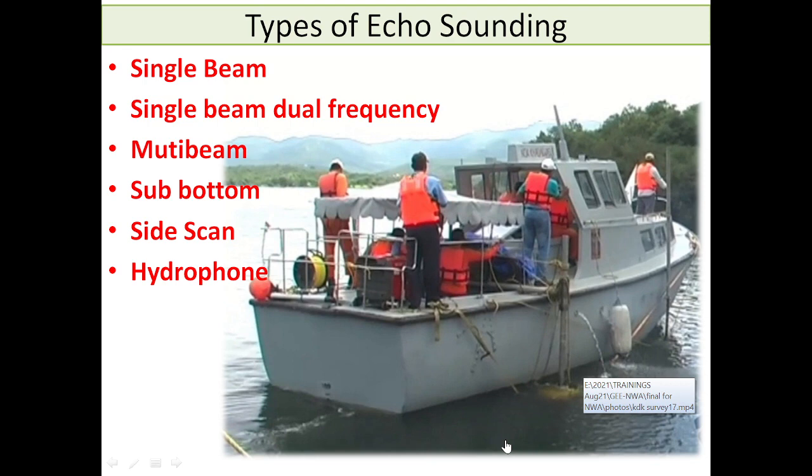That's going to give you a very interesting idea, and then you can say, with this experience I am able to tell them which methodology is going to be beneficial for what type of reservoirs. So CWPRS has done this, and we produced an output based on this, which could give you a guideline sort of thing. A single beam is one beam just going at a point and then comes back, then the boat moves on, then at the next point takes a measurement. So the in-between portion is not measured, which is mathematically modeled and analyzed.